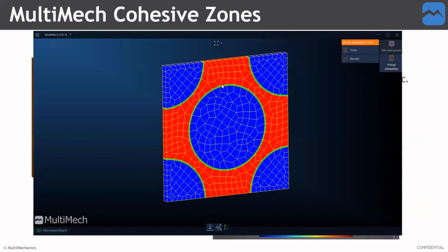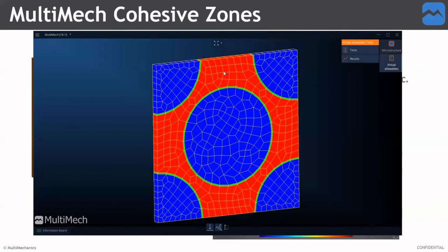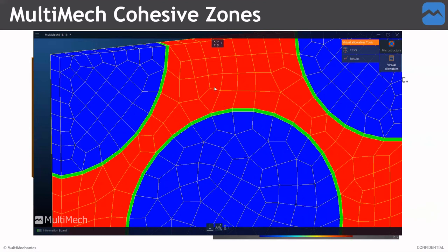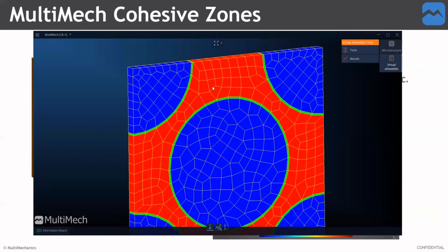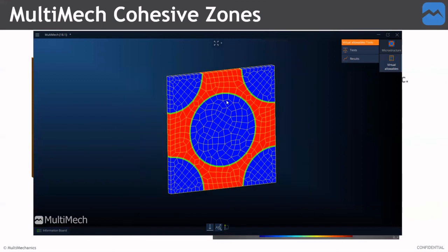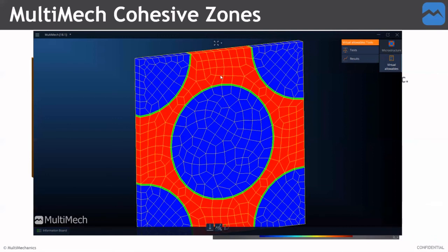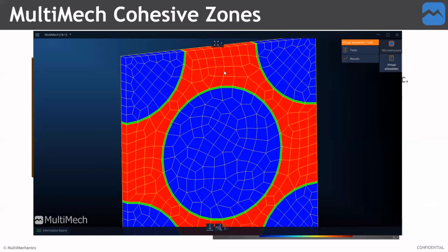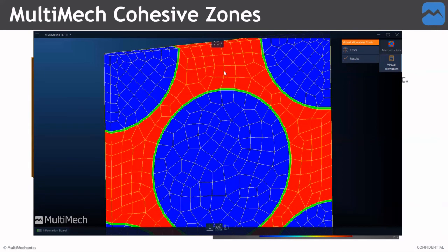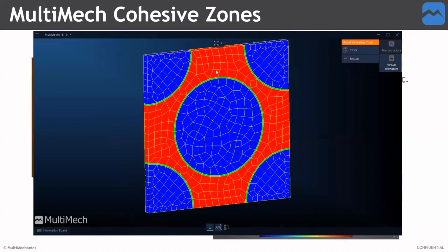to represent this as another microstructure. So if we want to represent it as a more porous, either closed cell, open cell foam, for example, we can represent this here. So we don't necessarily need to have the exact geometry here. We can represent this by another microstructure. And we've made some open cell foam RVEs that we're currently implementing, and it's really customizable up to the user. We do have the automatic microstructure generation tool, but we're not limited to what can be created through that. Even though that has a lot of different microstructures that can be made, we can also create microstructures by hand and implement them into your models.